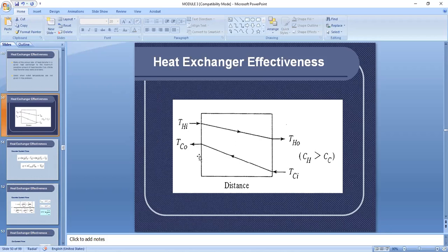The orientation shown here is counter current flow. And by the way, I think it was emphasized last year in our class that, of the two modes of contacting the fluids, indirect contact, it's the counter current flow that capitalizes more on, or uses more of, the energy of the heating medium. In terms of design, it's better than co-current flow or parallel flow. That is why in here the orientation is counter current flow. Now let's go to our equation.